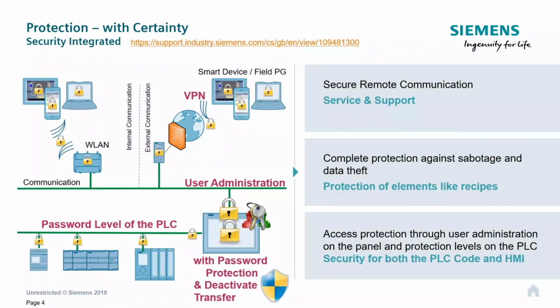Now, when we're talking about safety, and certainly with HMIs as well, of course, security is a really big point and a very strong point for Siemens HMIs. As you can see, there's layers and layers of things that we can go through on here. We'll start at the bottom. So basic things like password protection and the ability to deactivate the online transfer, so remote transfer for upgrade and modifications of the panels, so that can be locked down.